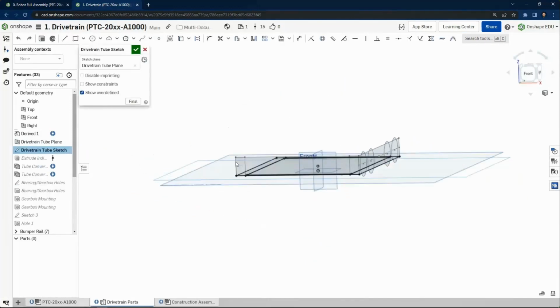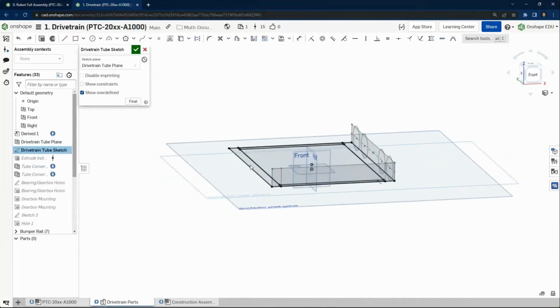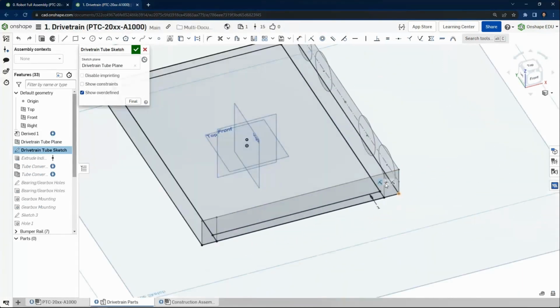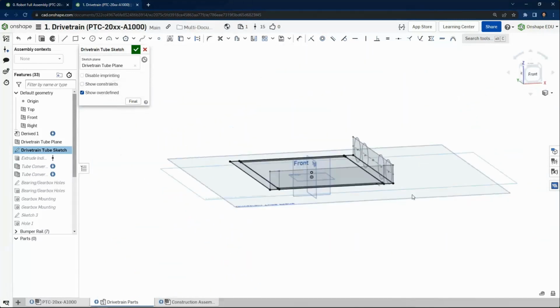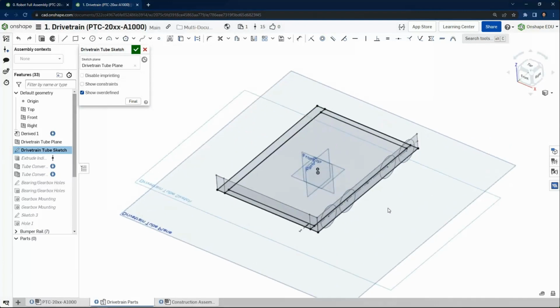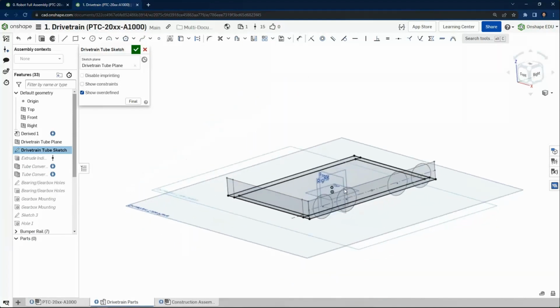And you can see that I actually didn't have to put many dimensions in because everything is coincident to different components of the driving sketches. What this also means is that if I need to update the driving sketch in the 0 document, I can have it parametrically update everything in this document, which is a really cool process. So everything is tied back to these sketches. It creates our one source of truth. Very easy to modify the design from one location.